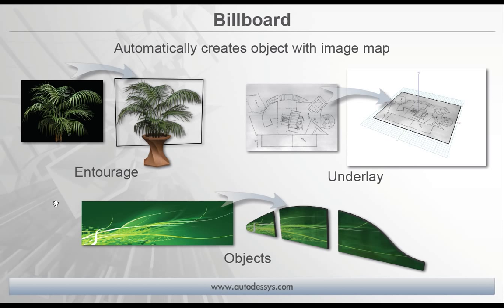We'll also look at the new Billboard Tool, which is a real quick, easy way to take any image and have it automatically mapped onto a flat polygon. It builds the polygon and automatically maps it on there for you. It's great for entourage items or maybe an underlay sketch. You can bring that in and actually scale it to the proper size, or you can use the Billboard Tool just to quickly bring in an image map and put it on a flat plane to further construct that geometry then using some of the other tools.